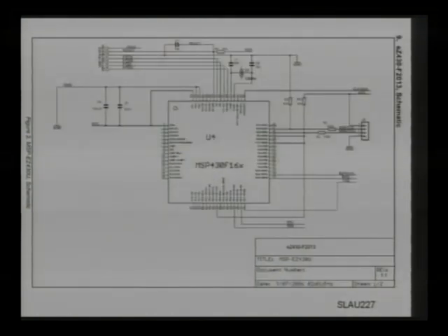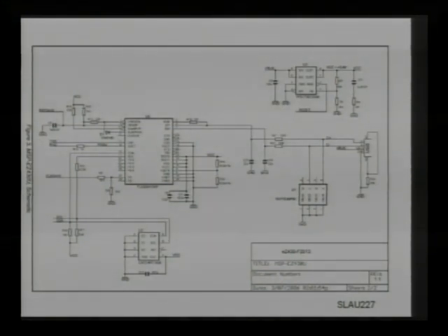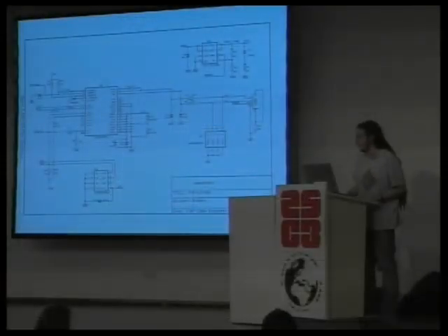So here we have the MSP430 along with the programming port, J2 on the right. You have series resistors and all of that stuff. And then there's a USB to serial chip, the TUSB 3410, which is similar to the FTDI chip, many of you will be familiar with. And there's a serial EEPROM, the CAT24FC16UI. Sometimes that part number varies. It'll be a larger EEPROM.